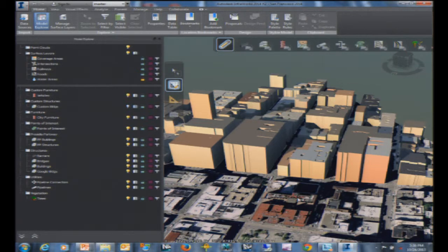So there you're seeing the aerials directly, and then if I zoom out to the outside of where we had built 3D geometry, it has another fun little feature where if you have shape files for buildings, in this case, this came from the city, and they had an attribute on the shape that had the number of floors in the building. So we could set up a little script that just multiplied the number of floors by 10 feet, I think it was, or some metric equivalent, and created heights for the buildings outside of the main part of the city.